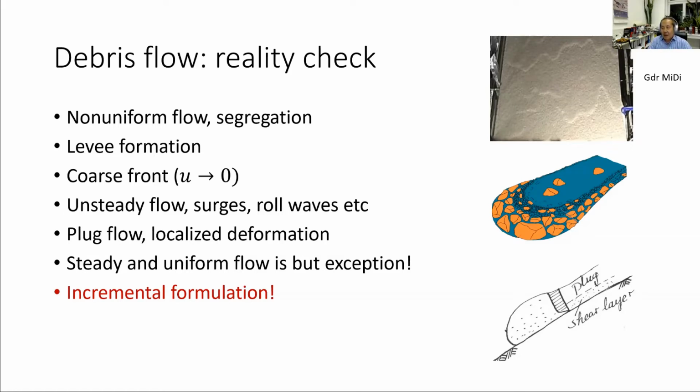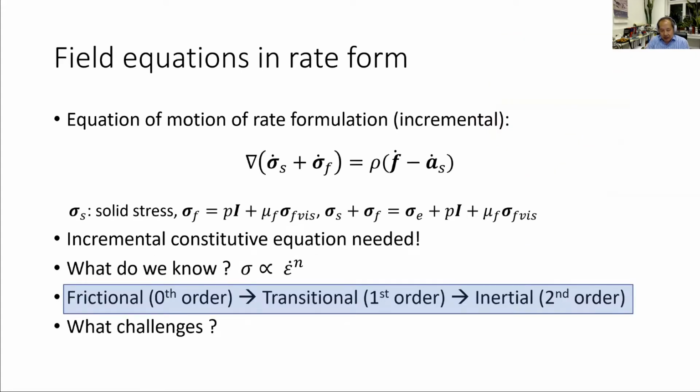And what's the way out of it? I believe we have experience and know-how in geotechnical engineering and soil mechanics. If we want to handle this issue, one of the possibilities might be, instead of the total formulation, right? You see, I just showed you the total formulation with stress. It's very important now to consider an incremental formulation, right? We use it in soil mechanics all the time, just because the material behavior is elastoplastic, so you just cannot use the total stress formulation. Now you turn to the incremental formulation.